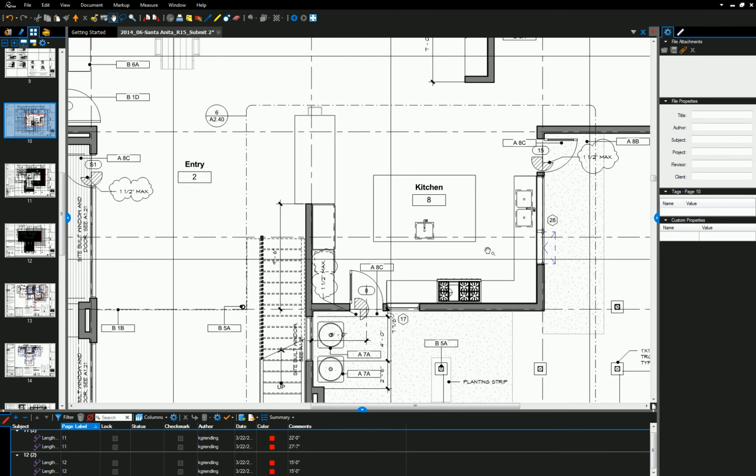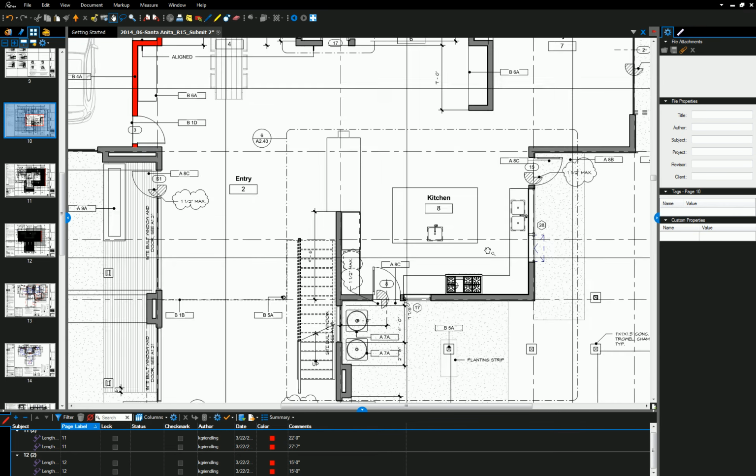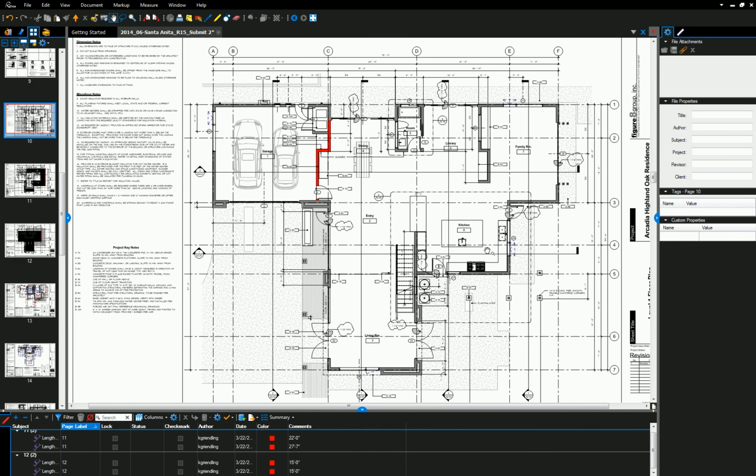Yes? So why are we creating another floor plan? Because we're recreating this construction documents floor plan. So I'm showing you a schematic floor plan and a construction documents floor plan, and then I'm showing you a schematic elevation, and then we're going to create construction documents elevations, that kind of thing. So you're going to develop both sets at the same time, which does happen in reality, sort of. Not to full construction documents level, but usually you'll have a presentation floor plan, and then you'll have your actual technical schematic floor plan. All right.